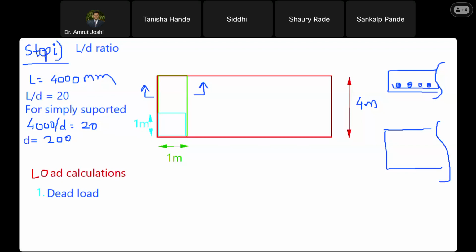So this is the slab. It continues. Now the reinforcement which is parallel, it will be seen like this, and it will be seen in double line because it's a bar. So this will be the bar diameter, isn't it? Yes, sir. So this is bar diameter 5. And you have the reinforcement going like this, perpendicular to the plane of paper. Are you with me?